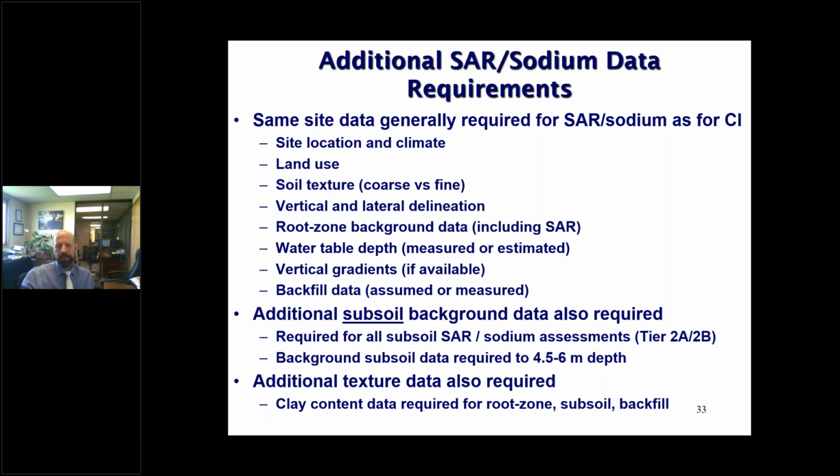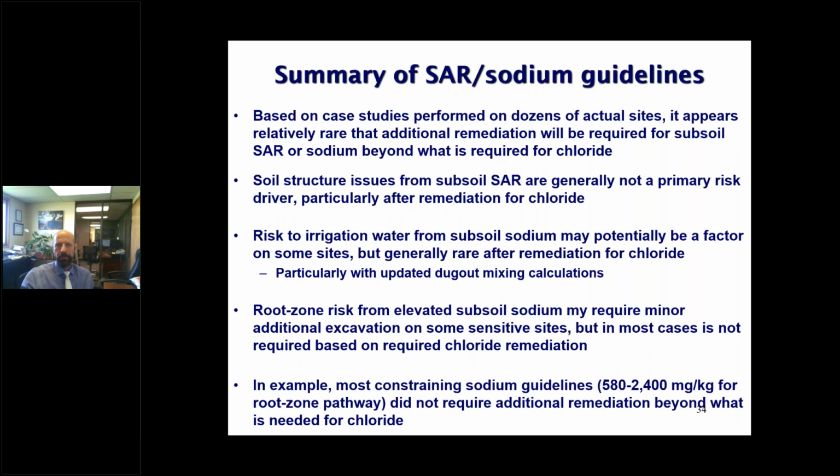And yeah, that's really the main thing. Just make sure you've got good background subsoil data. It gives more context for the SAR sodium assessment. And you also want to be making sure you get clay content data by hydrometer, even though you'll need sieve data now for the overall fine versus coarse. The SAR aspects are really relevant to clay. So you'll want a combination of clay and sieve data.